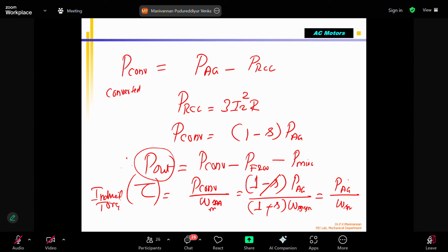See, from the stator supply voltage, magnetic flux is created. That magnetic flux is transferred to the rotor through the air gap, because between the rotor and stator there is an air gap. That is how much power is transferred. That power only is converted into mechanical power, not all the input power. After the losses, finally we get the shaft output, which is always lesser than the generated power.